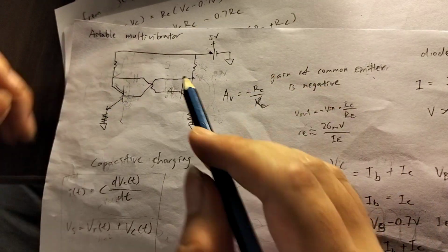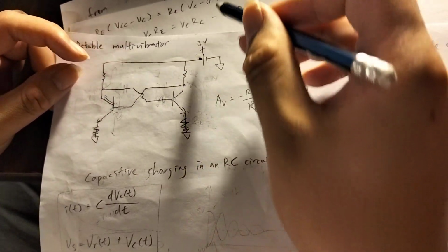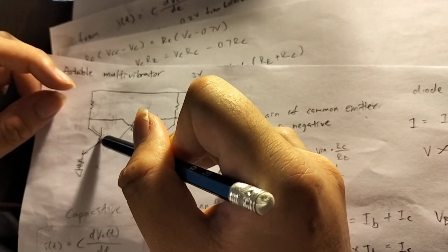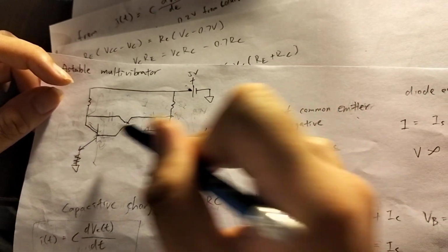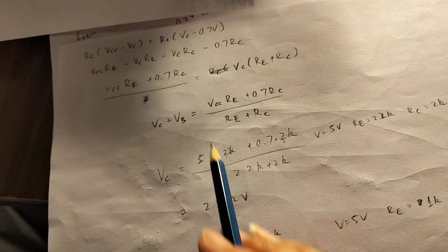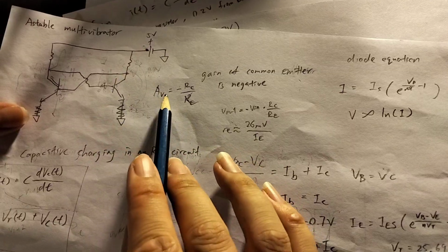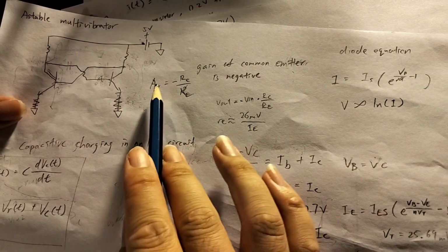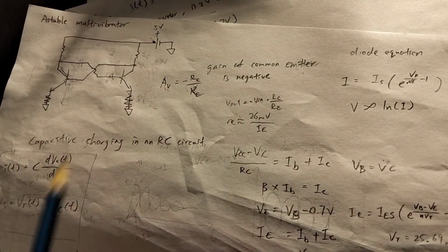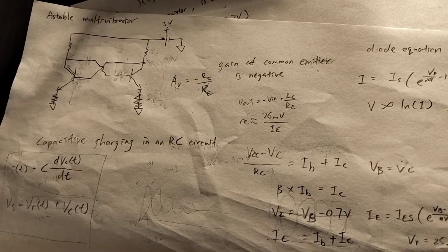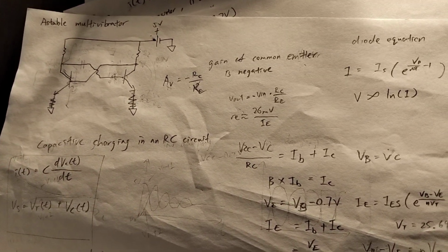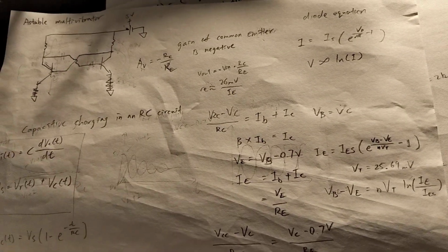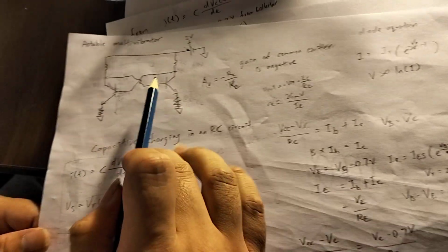Oh yeah. So basically, if we set the collector base voltage drop to be the same across both transistors, you can find the equilibrium state, and it's unstable for a configuration with a positive gain, with a gain bigger than 1. So then what actually happens in that case is it starts to swing, and then it finds an equilibrium state at a point where the gain becomes 1 again.